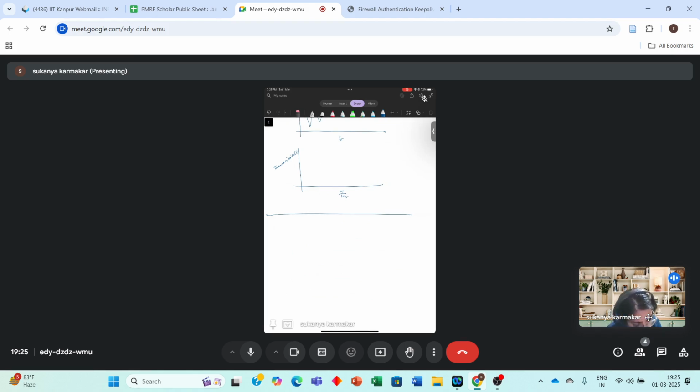So let's consider a frame like this. If you have a frame like this and you have a force P of t acting on it, and there is a damper as well, a viscous dashpot, and effective stiffness is k. So we write m ü plus c u̇ plus k u is equal to P of t. Till date, we have studied this.